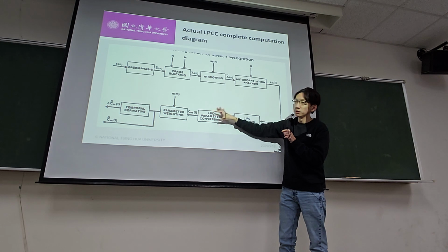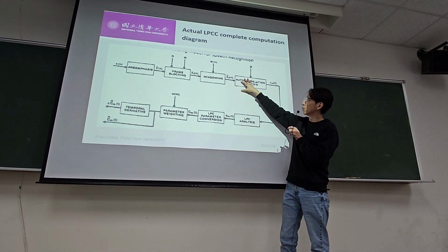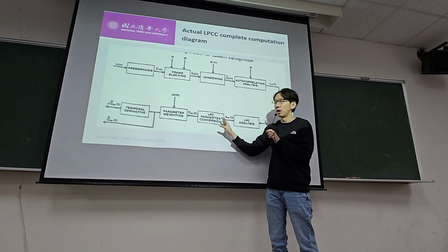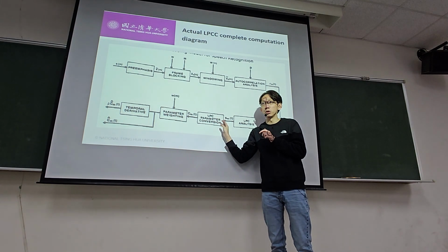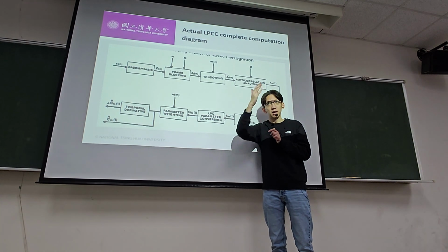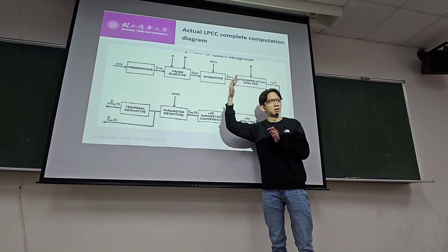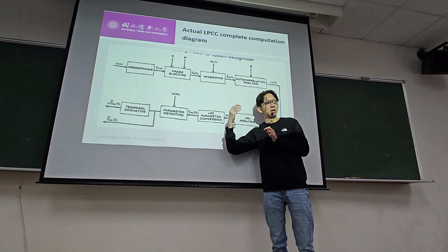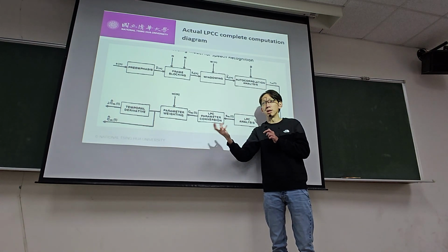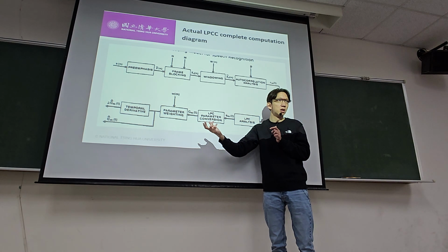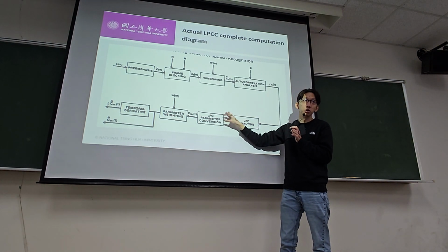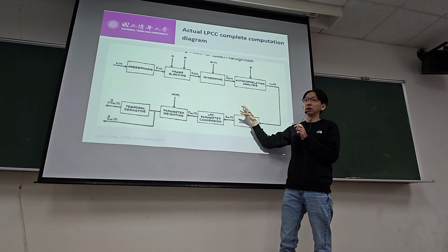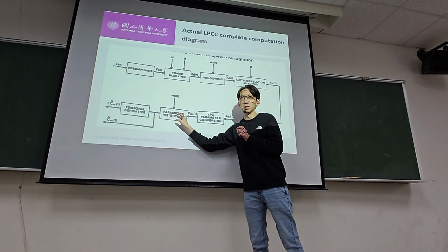The reason we do this is because of LPCC. When we do LPC analysis, the alpha coefficients relate more to the filter, the spectral peaks. The error signal of the LPC analysis is the source. So what's left as the alpha coefficients relates to the filter, and you take the filter to additional cepstrum analysis.